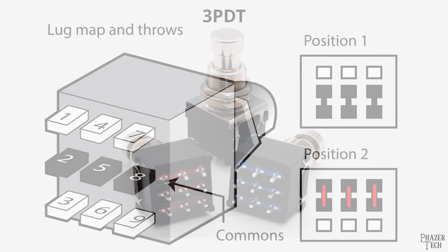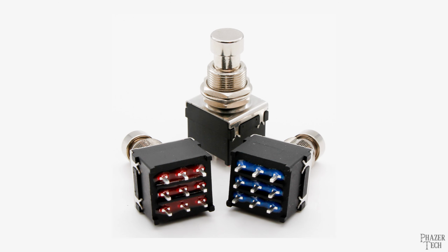Now, since this is a foot switch, it uses a latching button that's meant to be pressed by your foot, and these are commonly found in guitar effects pedals. When the button is pressed, it latches down into one position, and when it's pressed again, it unlatches into the other position, and continues to switch back and forth between these two positions each time it's pressed. This means its operation is exactly like an on-on toggle switch or slider.